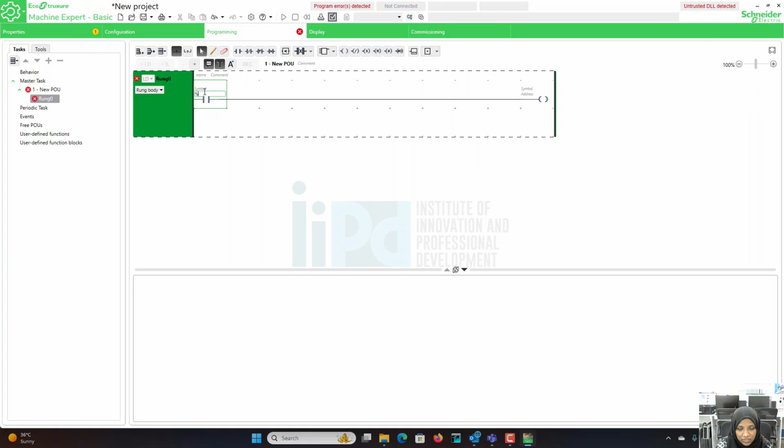So now I don't need this one. We'll give the address of the Schneider. When it comes to the hardware part, you might have seen it has a word level address. Inside the word you will have 16 bits. Each and every bit will have an address. In the hardware of the Schneider, we can see the hardware inputs. You have 14 inputs, and your outputs will be 10 outputs. The addressing is at word level, and if you are using an input, the structure will be I0.0. And again, it's a compact model. A compact model means the CPU with the inbuilt IOs.